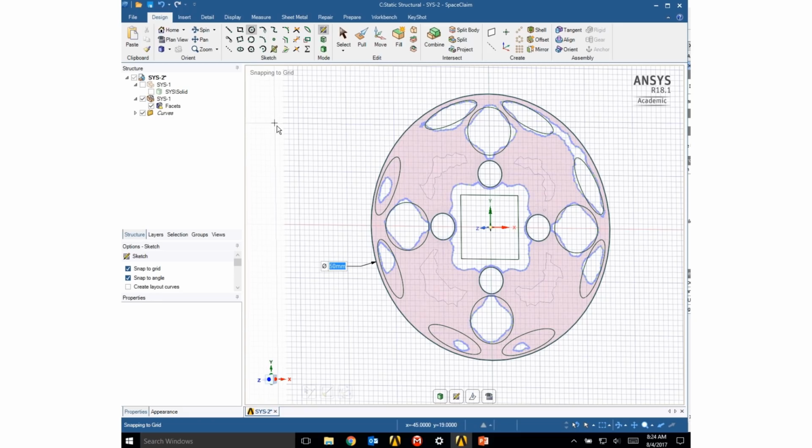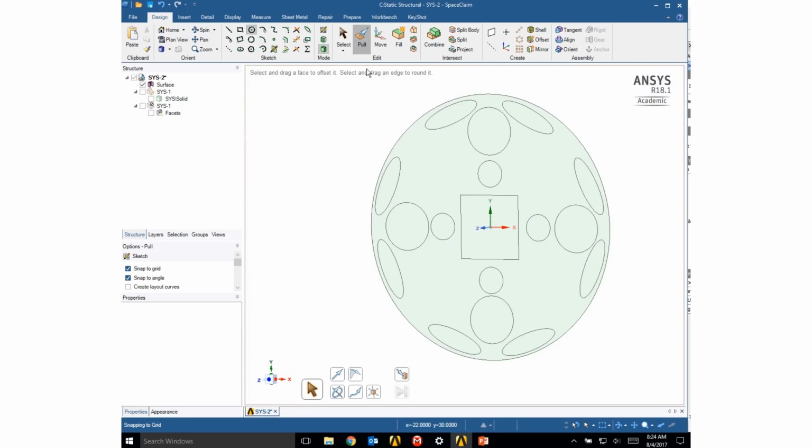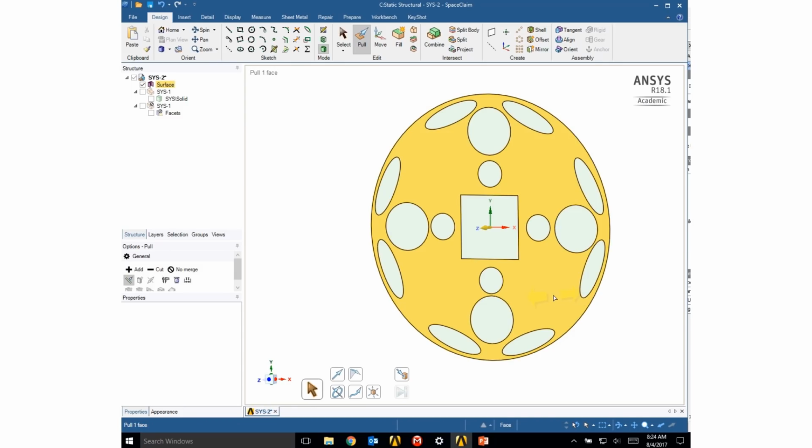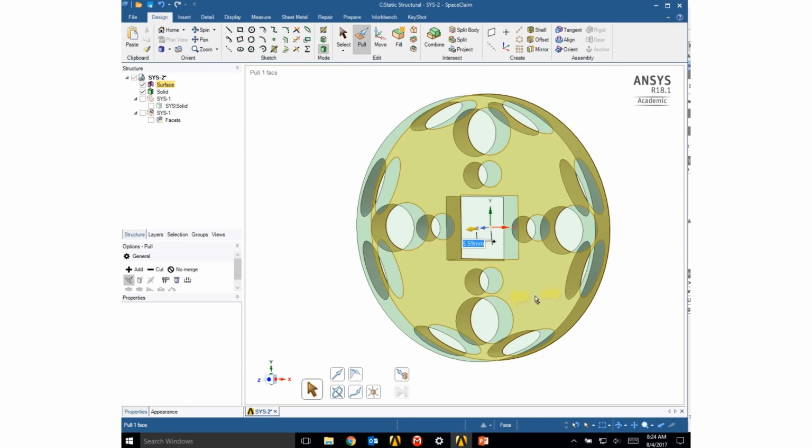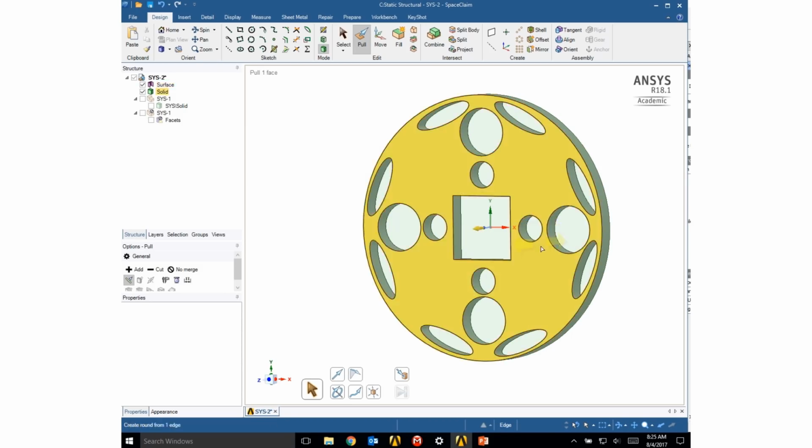we can go ahead and pull this into a new geometry. To do that, I'm going to get rid of everything that I'm looking at except the lines. So if I come over here and unclick that system, now all I'm looking at are the lines of what I want to extrude or pull. So I can come and click on pull, come down and highlight this body and pull it, and this was 3 millimeters, so I'll go ahead and type in 3 millimeters.